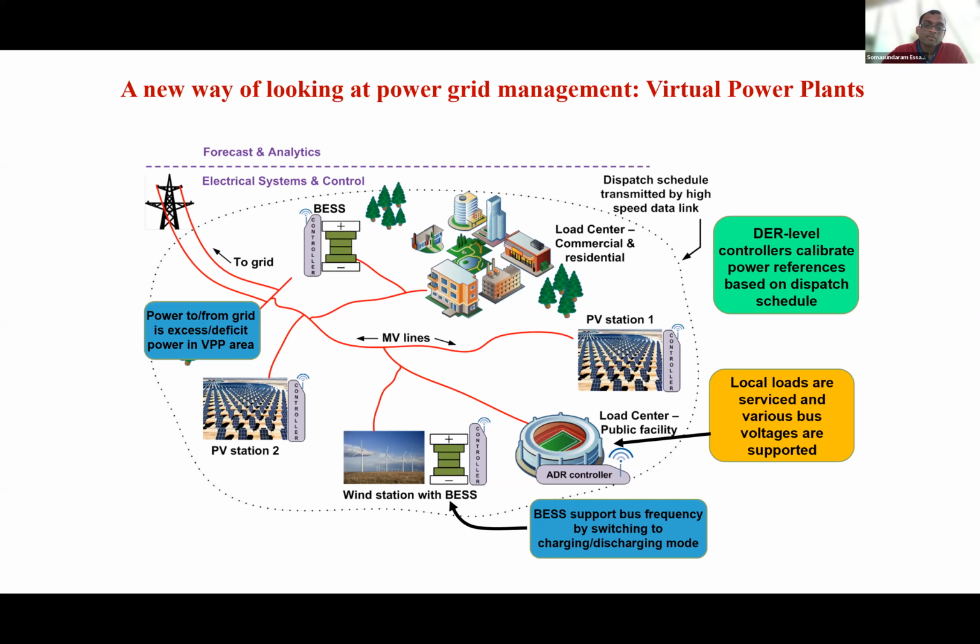You can meet that by using two methods, right? One method obviously is you can increase generation here, or you can see this is connected to the larger power grid, so you can increase power generation at one of your large power stations, or you can increase power generation from any of these guys, right? But what an ADR does, the second method, is you can meet that same increase in demand from the city by reducing the demand at a large factory or a public facility.